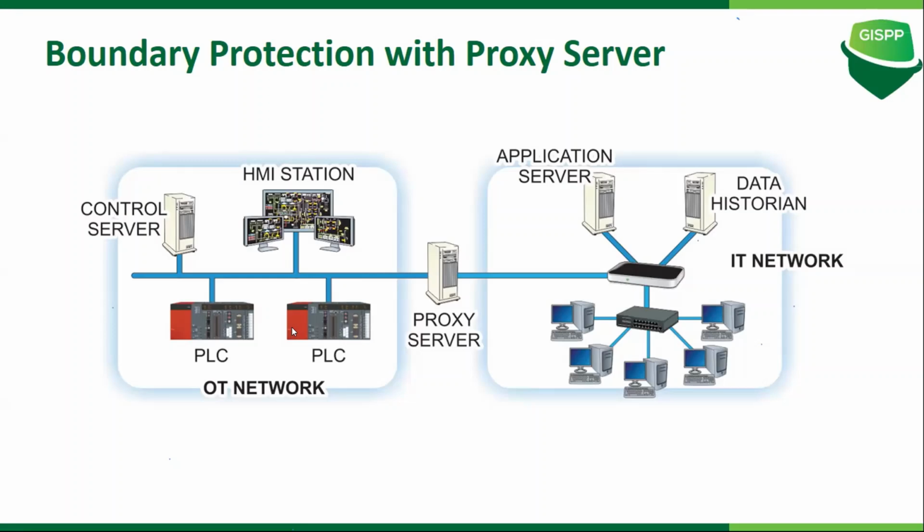During this filtering process, each packet is disassembled, evaluated, and reassembled, making sure it is of proper use, and that definitely slows down the process. But in an OT environment, we cannot touch availability. So these proxy filters, or the firewalls that are configured to view the entire packet for consistency or to check that appropriate ports are being accessed, we provide the basic rules to ensure that if you are taking certain data to the data historian,